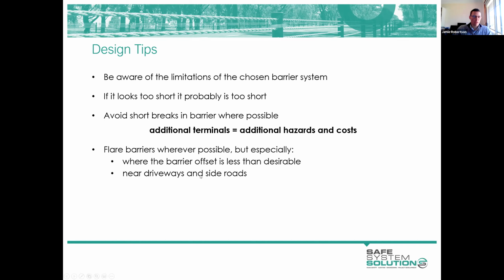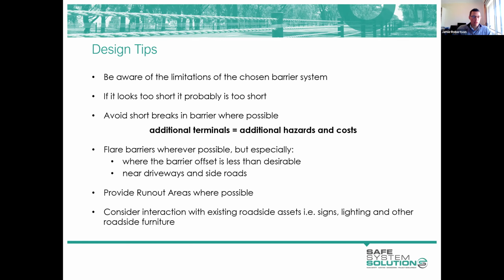Flaring barriers in constrained situations provides better shielding of hazards. It provides you with the most effective barrier in terms of shielding that hazard. Provide run out areas wherever you can, and really do think about everything else that's happening at the roadside.